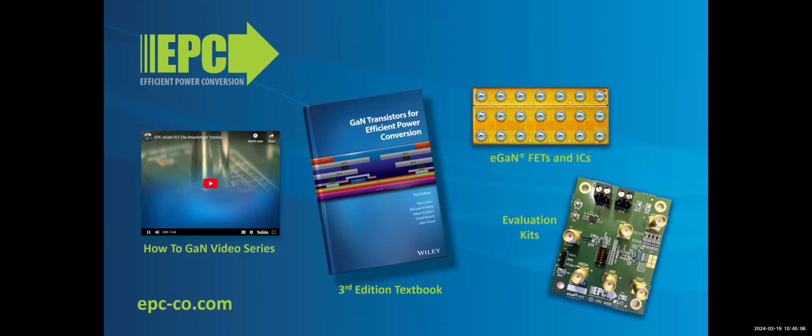From the winding isolation, usually a safe value is 5 volt per nanosecond. 5 volt per nanosecond is what our reference design does. That's what we usually recommend. And what I saw our customers doing is two different things. Either they go 5 volt per nanosecond and they go directly to the motor without doing any filtering at all. And usually they also do integrated motor design. So that is also reducing the problem of EMI. And there's no problem for the winding insulation in this case.